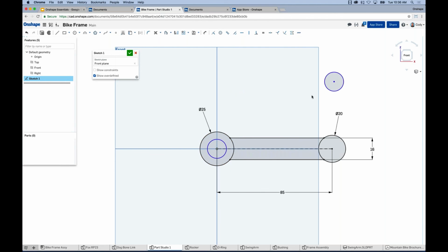Same thing over here. I want this circle concentric with this circle. Left click, select it from the toolbar. Right? So, it doesn't matter what the constraint is, whether it's perpendicular, parallel, tangent, equal, the process is all the same. It doesn't matter what the mates are. Just select the geometry involved, select the constraint from the toolbar. The last thing we have to do here is add a dimension to our sketch, which should be a value of 12. And now we're back to a fully defined sketch.